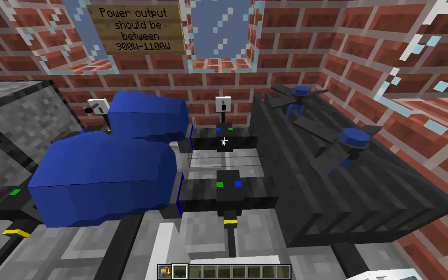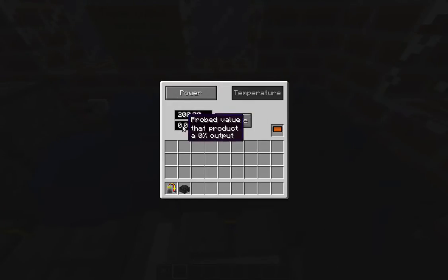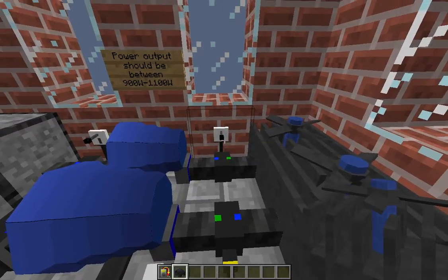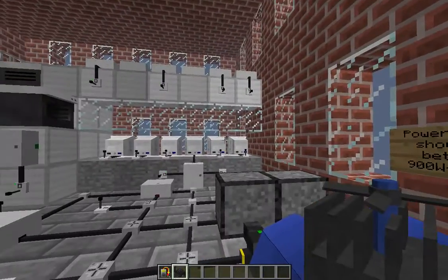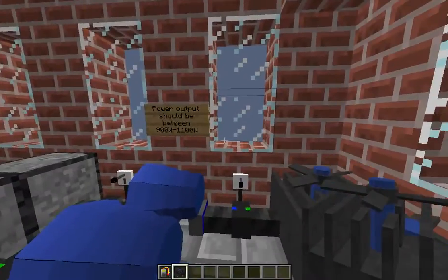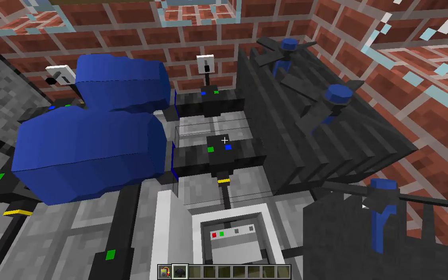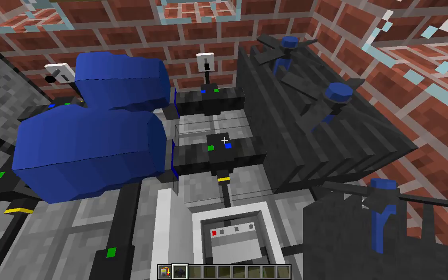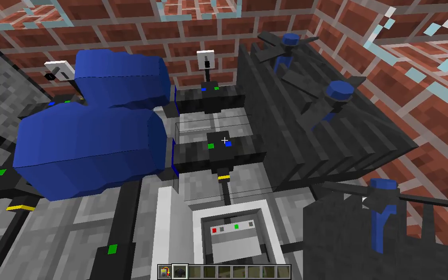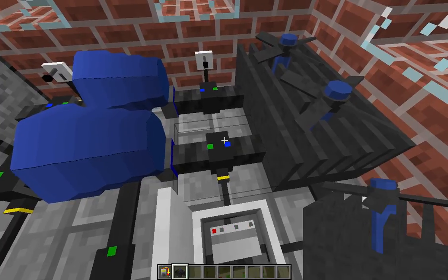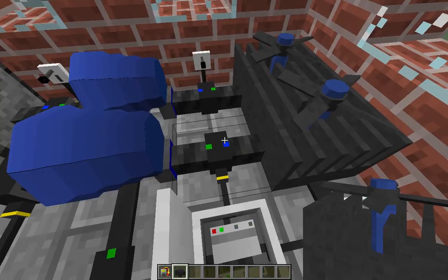Similarly at the end, this guy measures the temperature between 0 to 200 degrees Celsius and sends it to this little wireless guy, which is going to send him over there to the control room. This guy here does a similar thing, except his value is from 0 to 100 degrees Celsius. Now it's simply because it's easier for me to write out equations with stuff that's 0 to 100 than 0 to 200. But it can be whatever value you want.